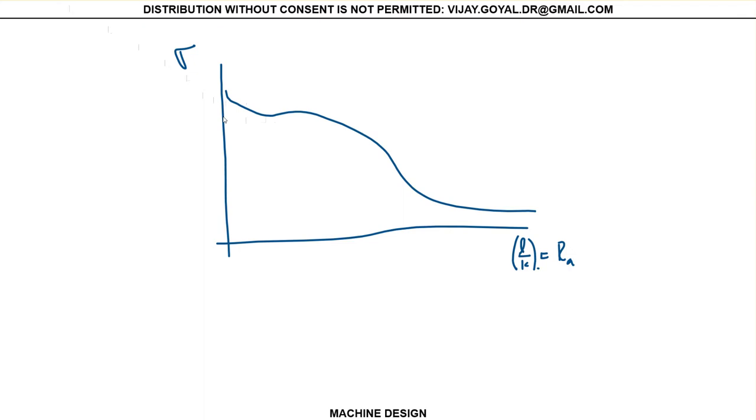Although using the J.B. Johnson, then your curve actually becomes like this, where this is the J.B. Johnson and this is Euler. And what we are trying to say here is, when you're working in this type of problems, for a particular slenderness ratio of the problem, you're going to have an availability of the stress or the load, right? So this is how much it is really available. This is the max you can possibly have. This is the amount available, sigma available.